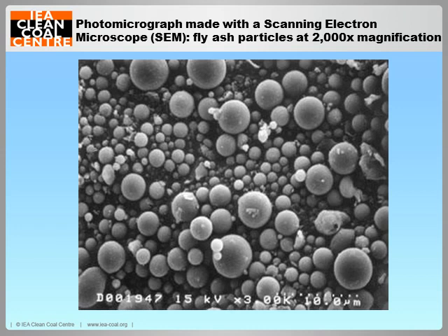Fly ash is one of the residues generated in coal combustion and comprises the fine particles that rise with the flue gas. In coal-fired power plants, fly ash is generally captured by electrostatic precipitators or fabric filters, depending upon the source and type of coal and its characteristics. The components of fly ash vary considerably, but all fly ash includes substantial amounts of silicon dioxide, both amorphous and crystalline, and calcium oxide, both being endemic ingredients in many coal-bearing rock strata.